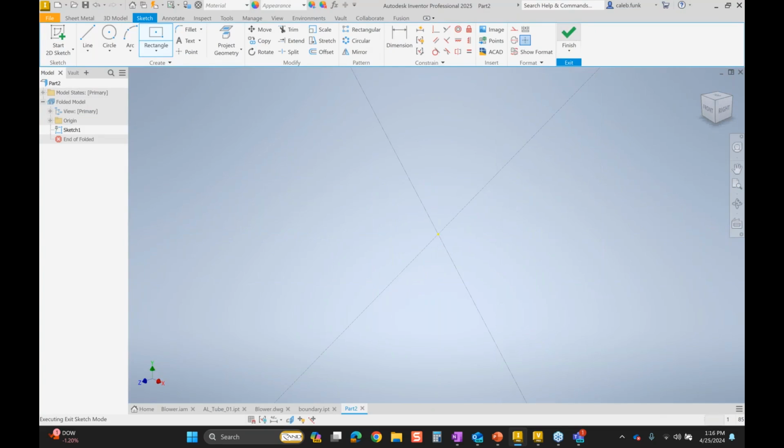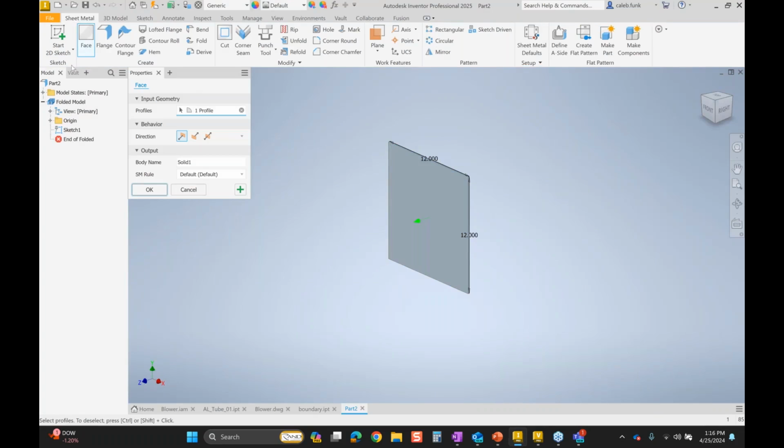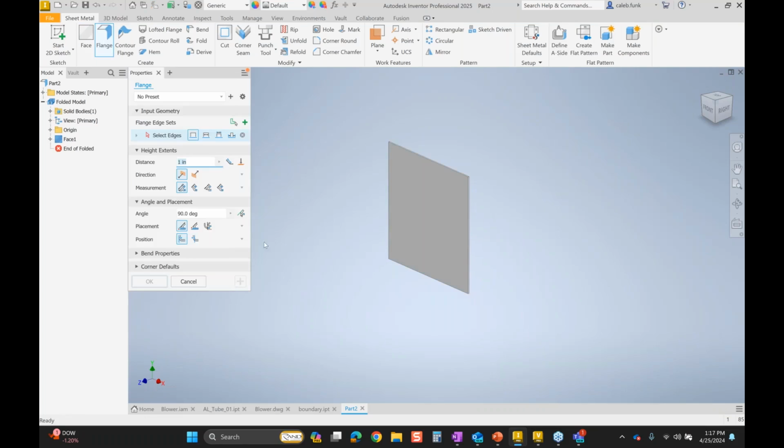Now, as I start to take a look at these sheet metal tools that we've had, they are all in these panels now. We don't have them anymore in separate dialog boxes. Not a whole lot here, this is pretty standard. It almost looks like the dialog box. The flange command gets interesting to me. It honestly becomes easier with how we access these things.